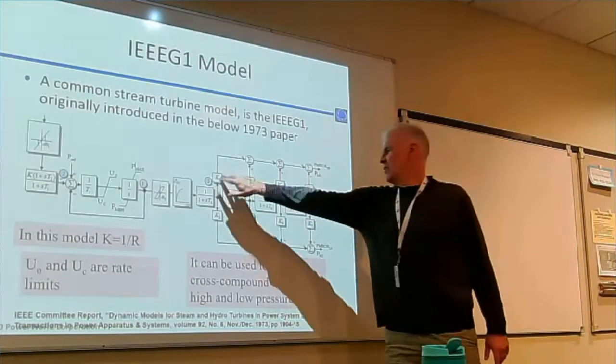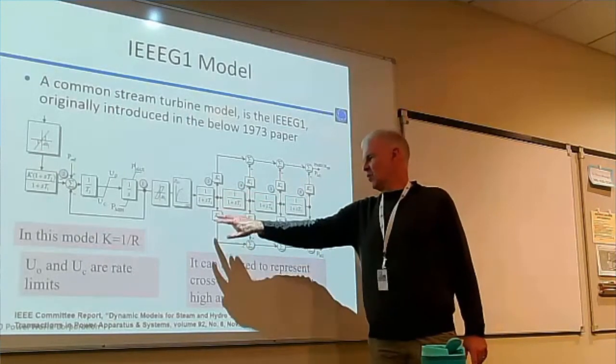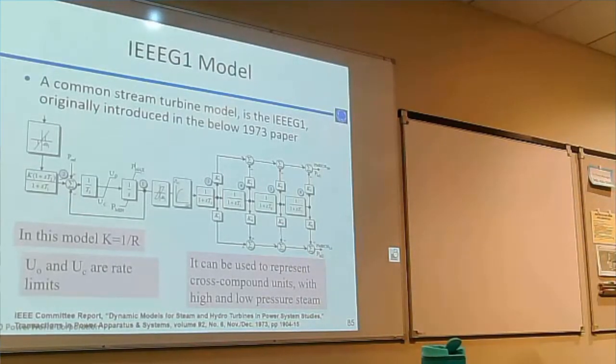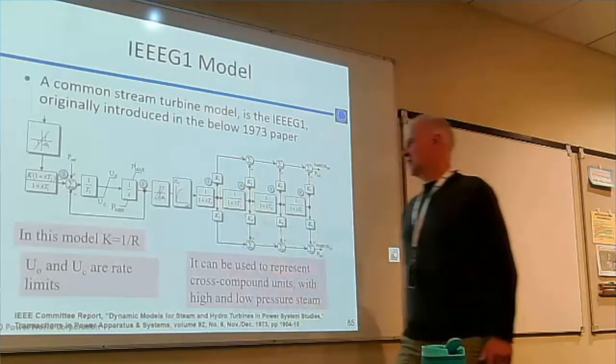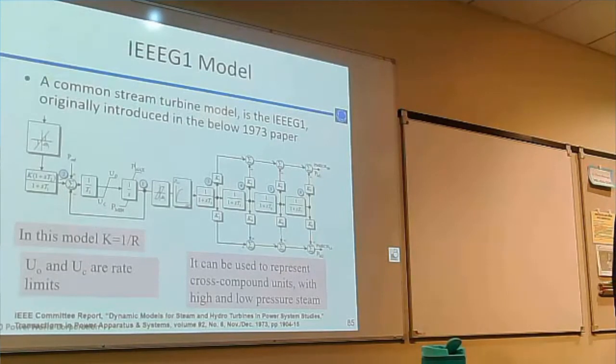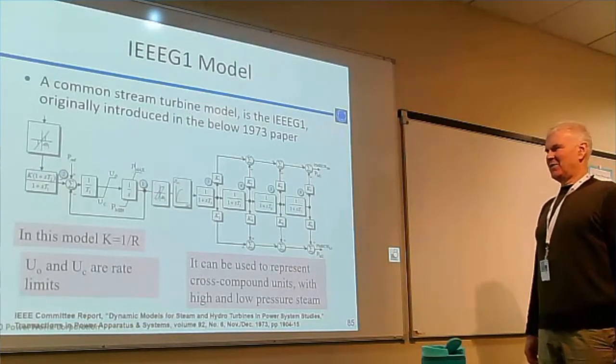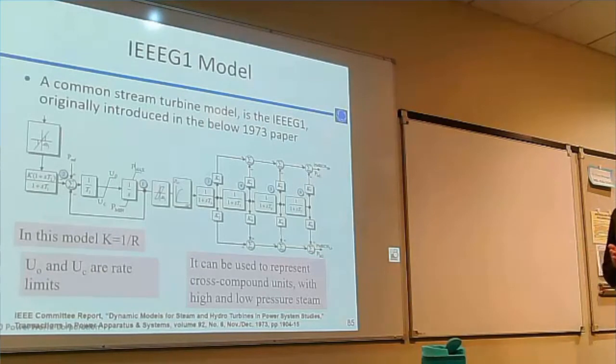The idea here is the K1, K3, K5, K7 should sum to 1, and the K2, K4, K6, K8 values should sum to 1 if they're being used. We have had situations where somebody inputs a value of K1 being like 20, and that causes problems. Simulator normalizes. These are all things that we try to fix as much as we can, but ideally, you're given good data. When you fix things, you don't know that there's a problem. For a while, there was a governor that had a negative R value, which was causing problems. But that's been fixed, I believe.